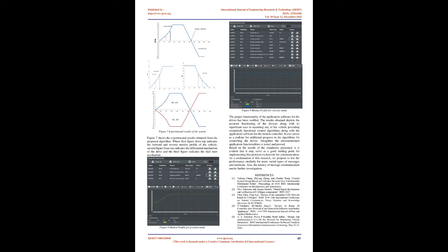Each and every device has its object dictionary, which includes records that are useful for the device configuration and many such initial operations, which is accessible through the SDO service. Electronic Data Sheet, EDS: it is a standard file format used for the object dictionary, which permits the services to update devices without difficulty. Standardized device profile. CANopen delivers multiple profiles, e.g. input/output, I/O, modules in CIA 401 and motion control in CIA 402 to facilitate the ease for the vendor's individuality.